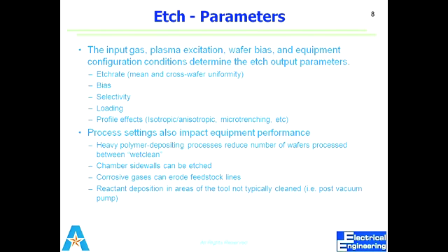This slide also talks about the same thing: the parameters that can change your etch rate and that are important for etchant selectivity. First, what is the etch rate? Of course, that is one of the important things. Bias, that is, what voltage potential difference you apply. You know that in order to have the bombardment, the wafer is always at the cathode, the negative potential, and that's why the plasma ions move towards the negative plate and bombard the substrate.